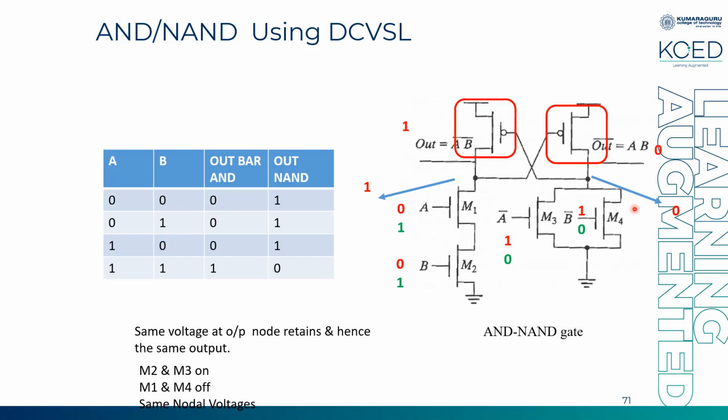So some transistor in this parallel block is on. Whether one is on or both are on, all the voltage here will go to ground. Again a 0 is maintained here. This 0 through this path turns on this PMOS, so this will have a 1. It will give a 1 since it is getting charged through VDD, and this 1 will act as an input to this PMOS. So this PMOS will still remain in off condition and output will be maintained as 0.